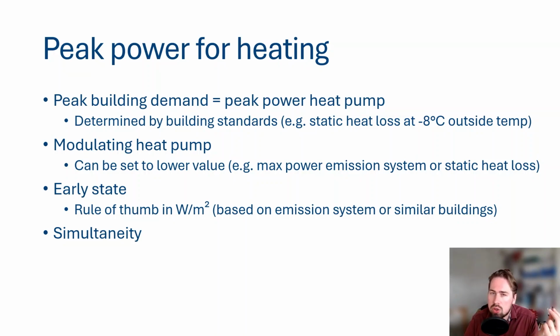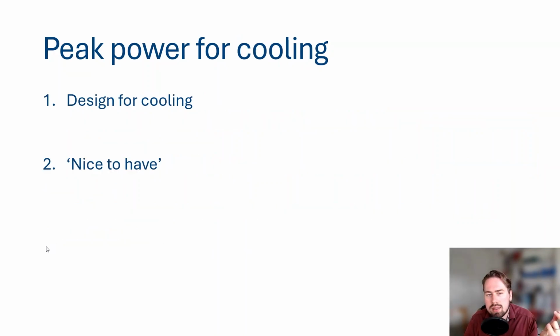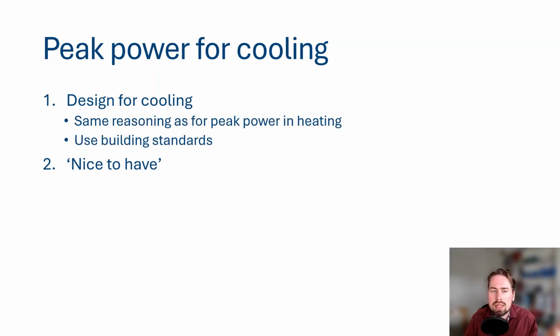Now, for the peak power in cooling, it's more or less the same story, except we can make a distinction here between different regions of the world, let's say. So first of all, you have buildings where the geothermal system is actually designed for cooling. Now, what do I mean by that? It's for the warmer regions where cooling is actually the most important energy consumer in the HVAC system. And then you follow the same reasoning as for peak power in heating. So you typically have a standard by which you can calculate the peak demand for cooling, and you size your emission system and your bore field based on that.